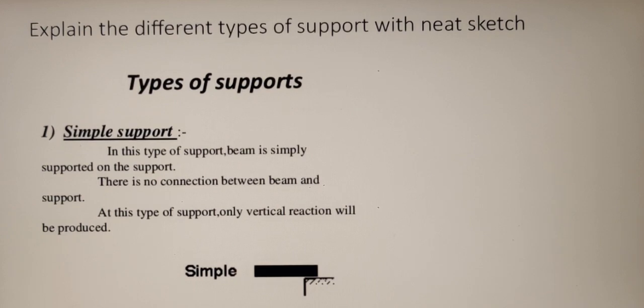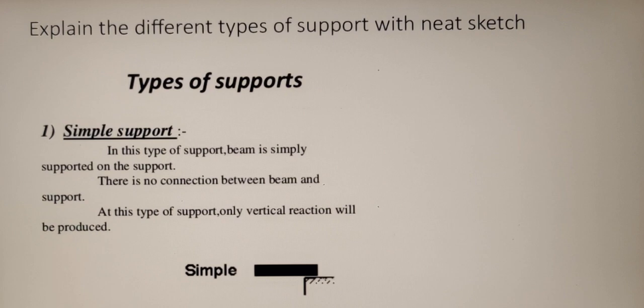So there is no resistance to the force in the direction of the support. Here the reaction will always be normal to the support. That is, there is only one reaction, the vertical reaction. So for a simple support, there is only one reaction at the support, that is the normal reaction or the vertical reaction.